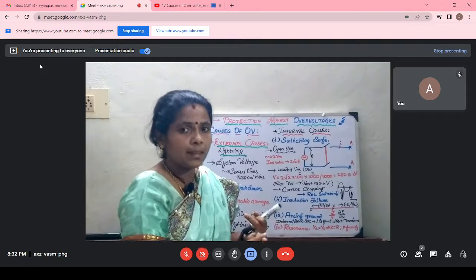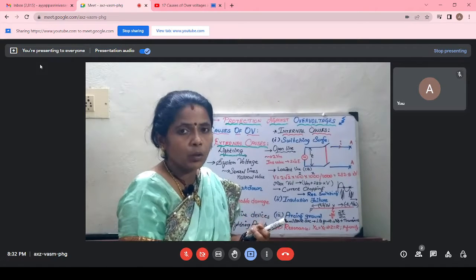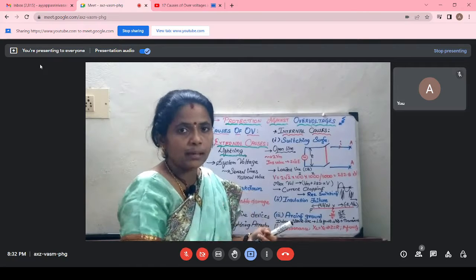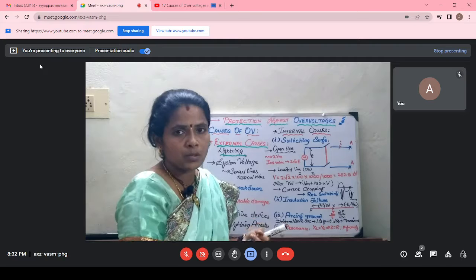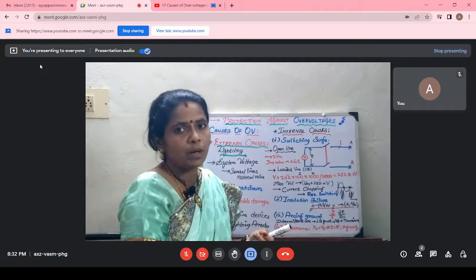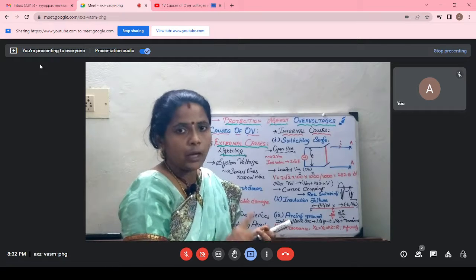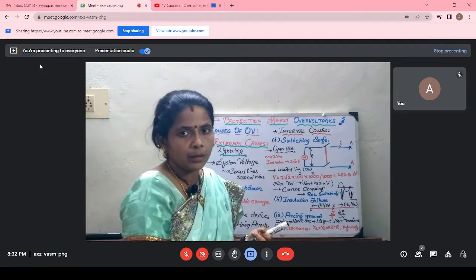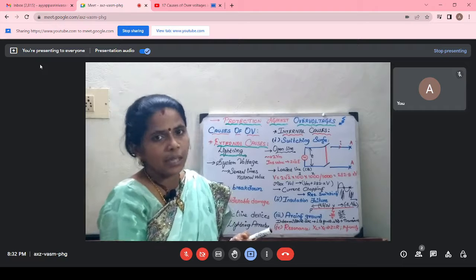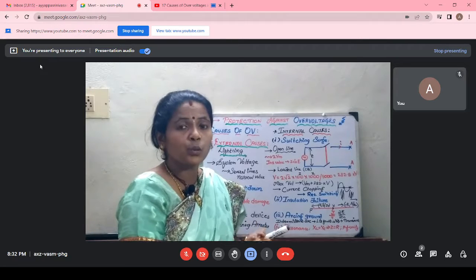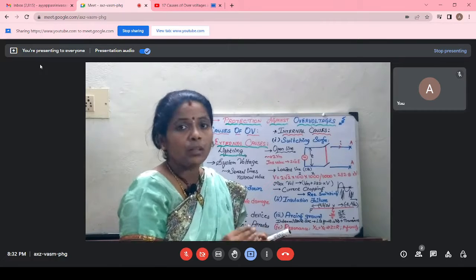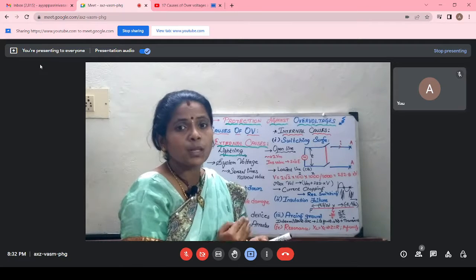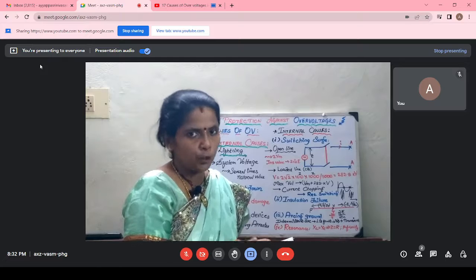The second thing is that whenever I do not connect it to the neutral, the zero sequence current, which would otherwise be circulating, is avoided. So these two advantages were there. I don't want to remove the line out of action if I'm not connecting to the neutral, and the zero sequence currents are eliminated. But this will not suit all conditions. Whenever a high fault occurs on the system, this might lead to considerable damage of the equipment, right?